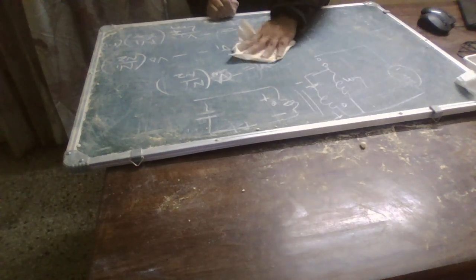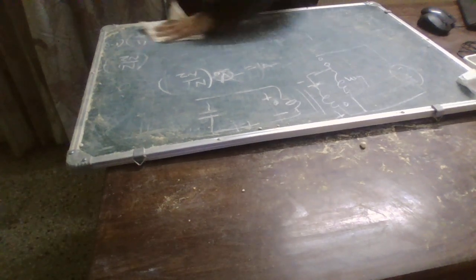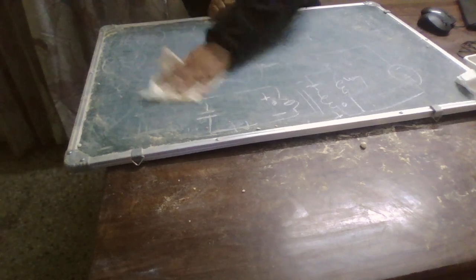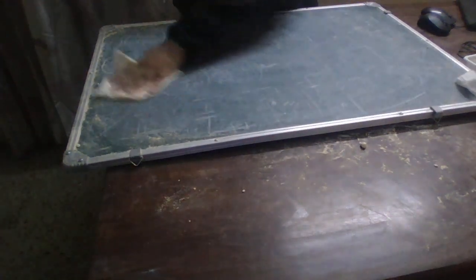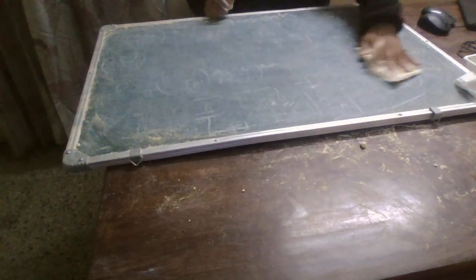So we have got the change in the transformer magnetizing current when the switch is on and when the switch is off. Now in steady state operation, we know that off and on should add up to 0.